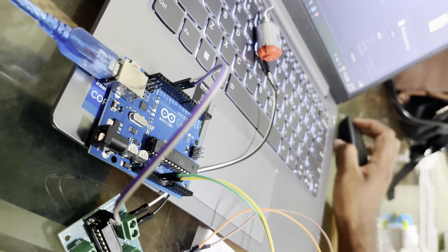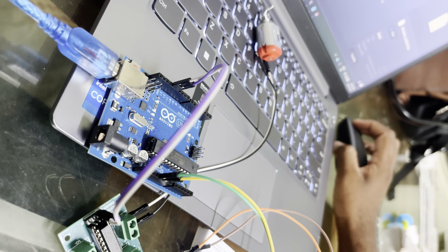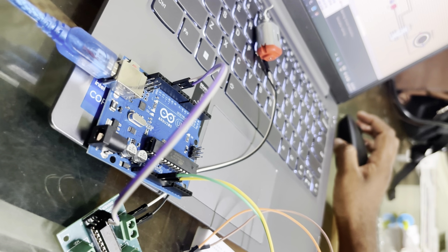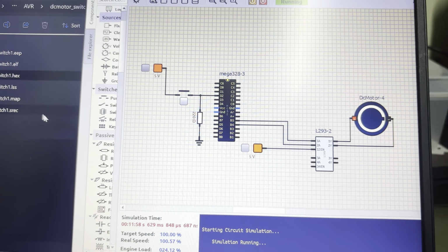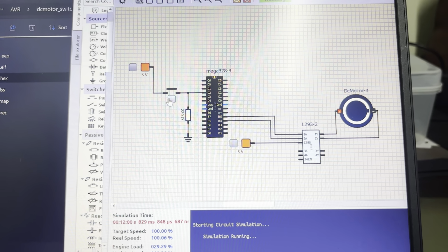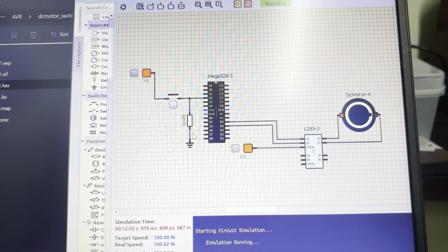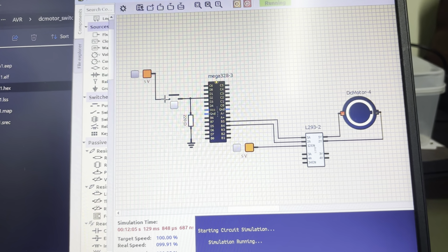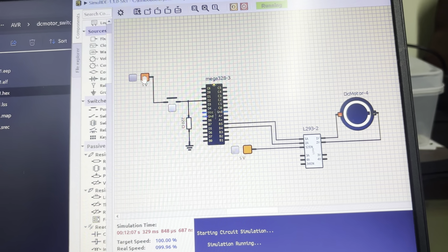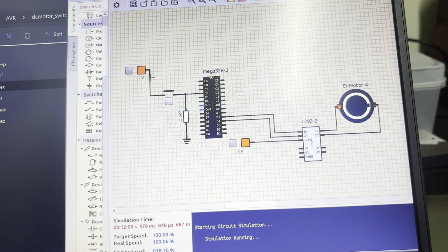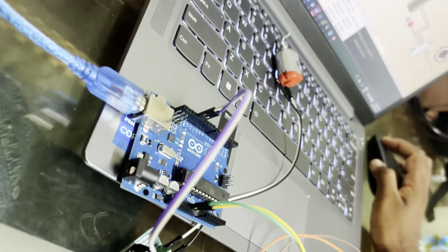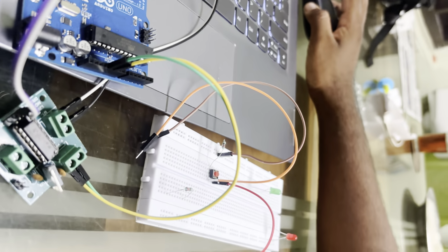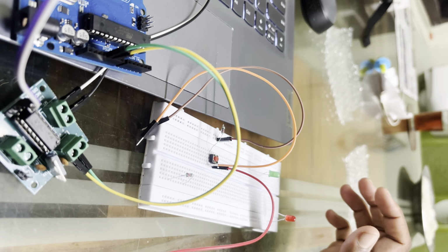Here I am going to show the circuit diagram for you. This is our circuit diagram. According to this circuit diagram, we need a pull down resistor from the push button to the ground, also another end of the push button to the 5 volt. Okay, we are creating this type of arrangement. Now this is our button arrangement.